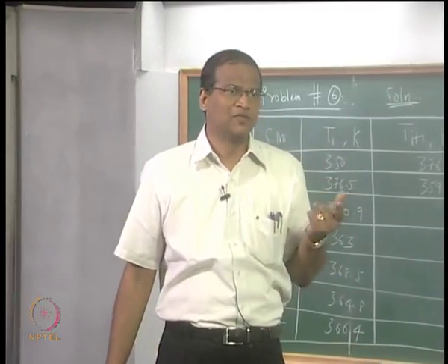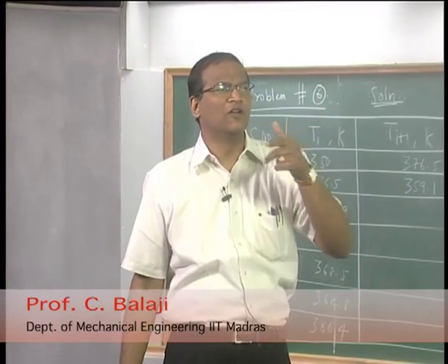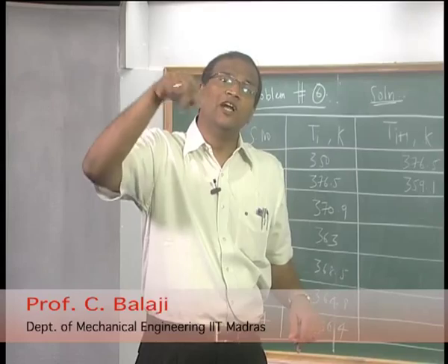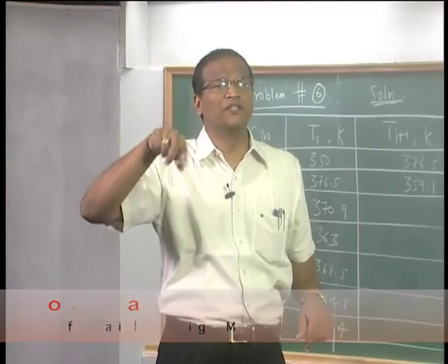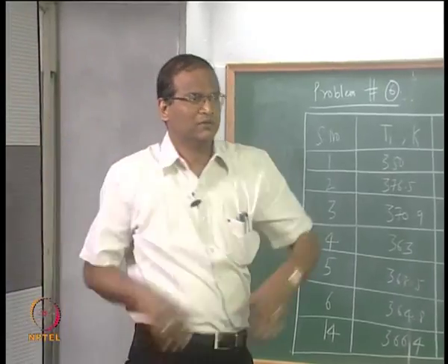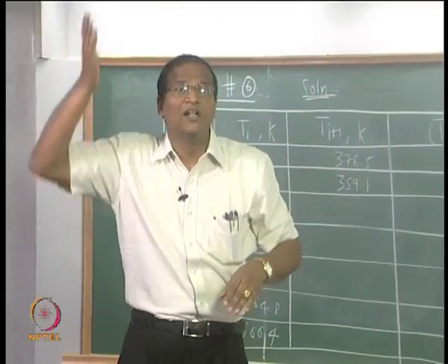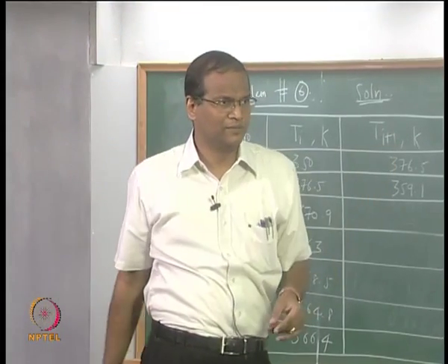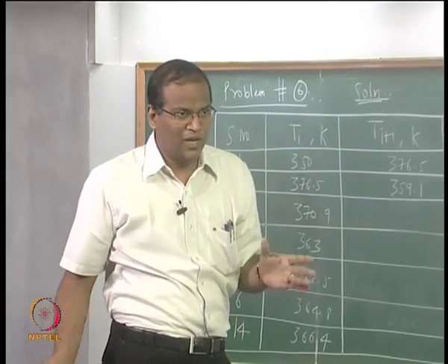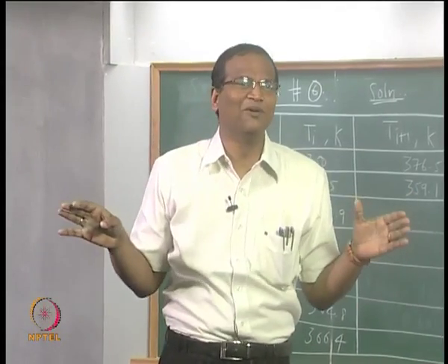That is basically because if you take f of T equal to Q total minus Q convection minus Q radiation, and take d of f by dT, that is a very strong function of temperature because it has a T cubed term. So it is not behaving properly, it is misbehaving.